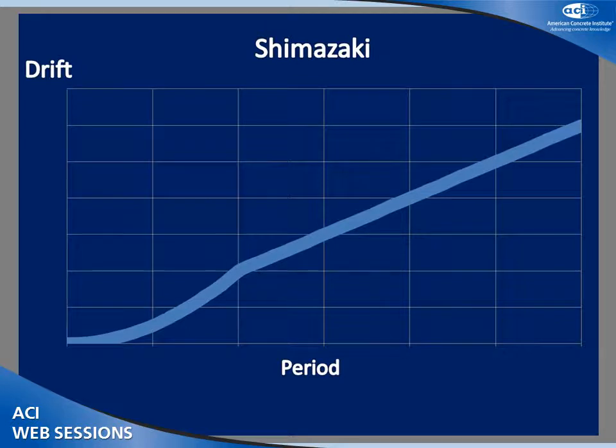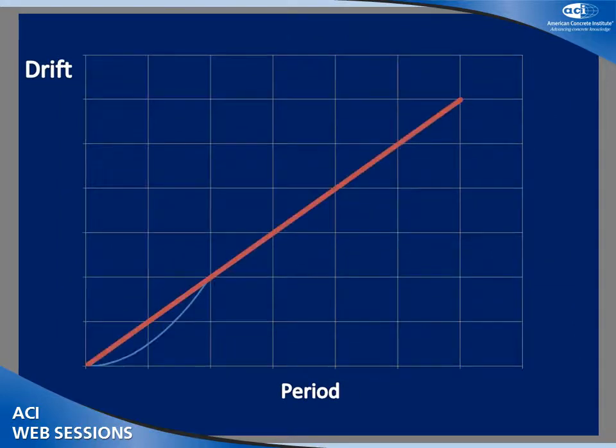Dr. Shimazaki, looking for a very sophisticated way to calculate drift by using the Takeda hysteresis, discovered that he could calculate the nonlinear drift by using a linear model based on 2% damping. It was that simple. The only thing he had a problem with was in the lower period range, in the nearly constant acceleration range, which he couldn't straighten out. And then in comes Dr. Lepage, I never know how to pronounce his name because he keeps changing it, and it's very much like the Christopher Columbus egg story, where he drops the egg on the table. He says, no, you can do the whole thing with a single straight line. Use a linear model, which was elegant, and I still believe in it.